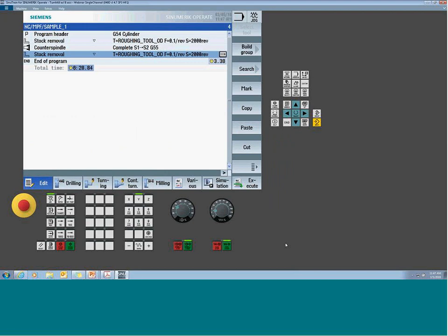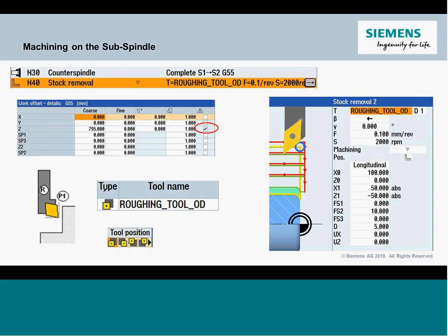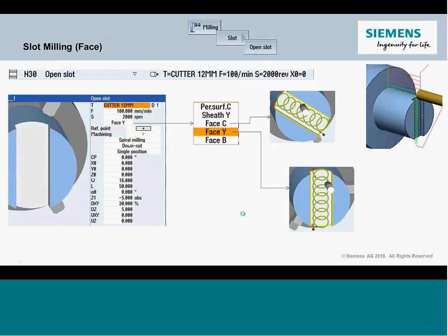So we start to get to some more intricate or interesting types of features. Let's do some milling. So come to the milling cycle, you're going to notice there is no beta and no gamma, because based on the orientation of the geometry, I tell it whether my face is on my peripheral surface. That's how we're going to know how to stage the B-axis.